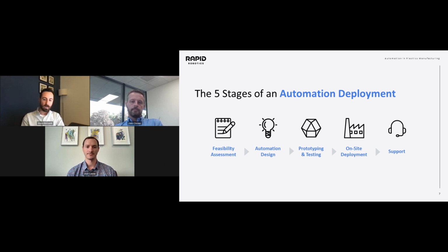Yeah, so I mean, I have my normal checklist of things that I'm looking for on a specific task, right? Cycle time requirements, throughput requirements, or hourly, daily, monthly volumes, some of the specific requirements for that task, whether that's inspection or otherwise. But more generally speaking, what I'm looking for is a simple, repeatable process that has as much structure as possible. Right. So, speaking to what you typically see on a plastics plant, parts are coming out of the mold structured and repeatable, right? However long you can maintain that structure is going to be best for automation, right?